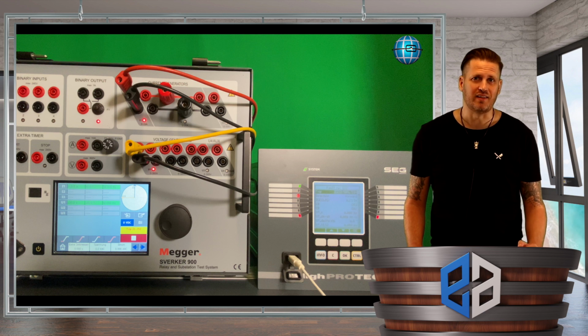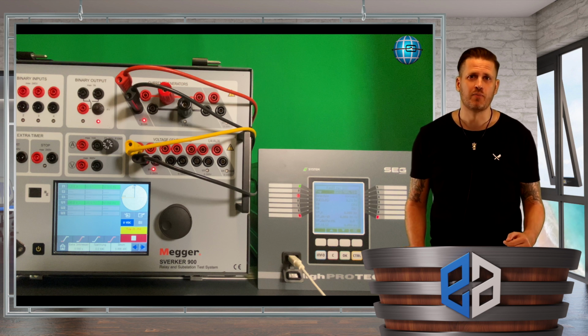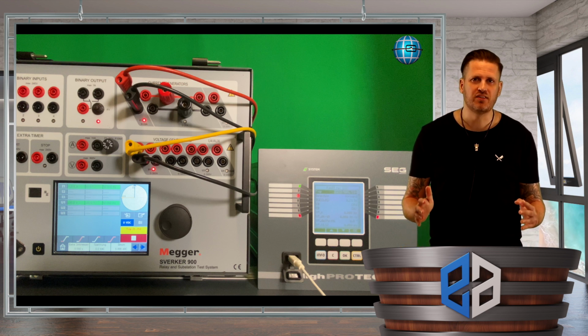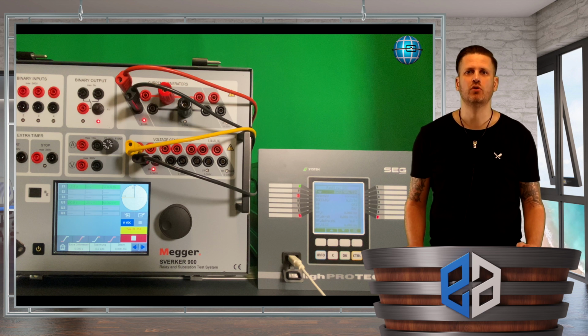Maybe a quick note at the end. Since insulation failures usually have a sudden character, it is also useful and quite common to do our tests shown here with so-called pulse ramps and to simulate zero states between the individual test points.